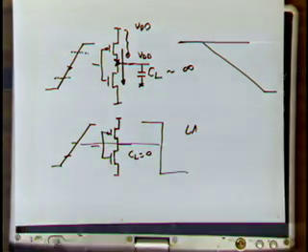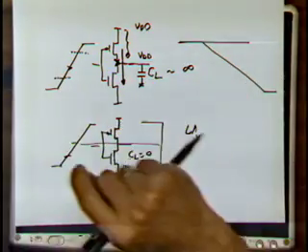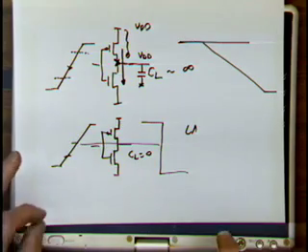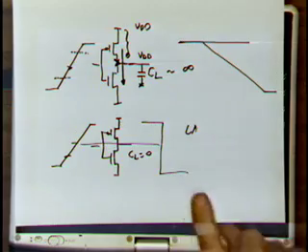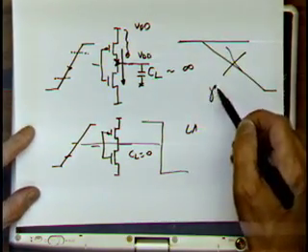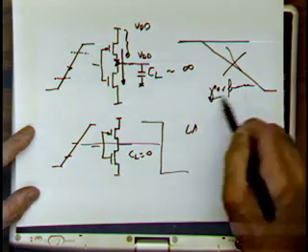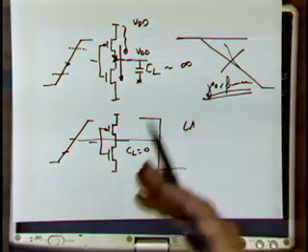Right? So, the problem, what we can conclude out of this, is that making your load capacitance larger, or making your output slope slower than the input slope, helps to reduce short circuit current. If I make the output slope faster than the input slope, I'm going to have a boost in short circuit current. Now, this one is bad for performance, so we don't want to have that. So like always, what we do is compromise. I want to get good performance and low short circuit current. What should we do? Well, we compromise between the two.